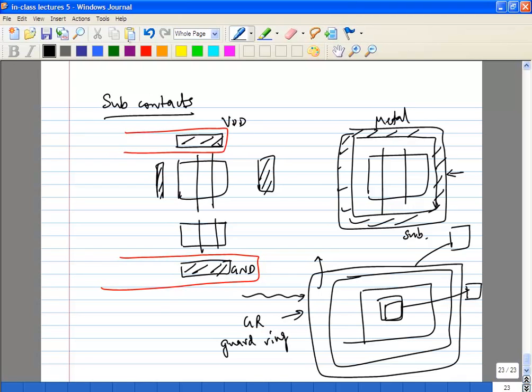Then we will connect those two contacts. Sorry? We will connect those two. Okay, so these two will be pads. So you'll have a bond ring. The idea is to increase the impedance between those two paths, so that at any time the noise current has a choice between which paths to flow, it will flow through the low impedance path. Obviously at some point it's going to be connected up, but you keep increasing the impedances along these paths until the point where the noise wants to split.